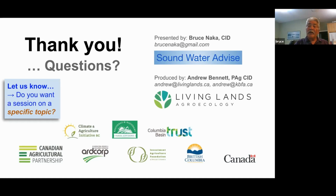Well, 40 PSI was for the larger impacts. The smaller impacts, and now the Nelsons and the Senningers and the various sprinkler companies that are coming out with some very efficient plastic type of heads, you can go down as low as 25 PSI and have them operate very well. So if you're talking the Rain Bird type of heads, the very minimum I would look at is maybe 30 PSI. Are they going to operate at 20? Yes, but not as efficiently.